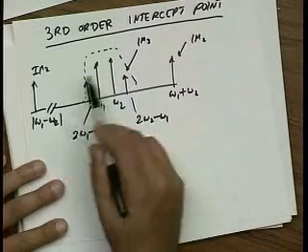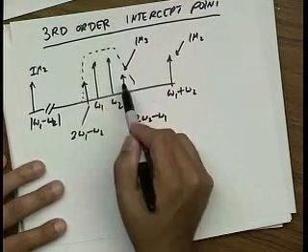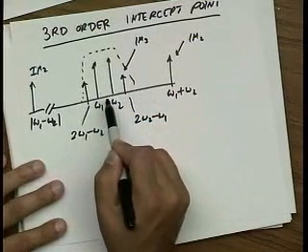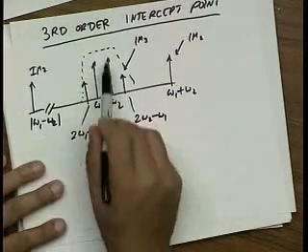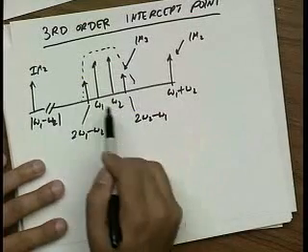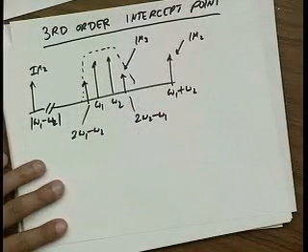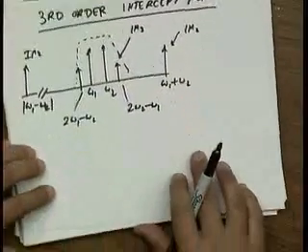So recall that I can't easily filter out these tones. You could say, well, you can make your filter sharper, but I can move these tones closer together, right? So in fact, I never really send tones, I always send modulation. So there's always going to be lots of tones close together that will produce this kind of distortion. So IM3 is particularly nasty because we cannot filter it out.